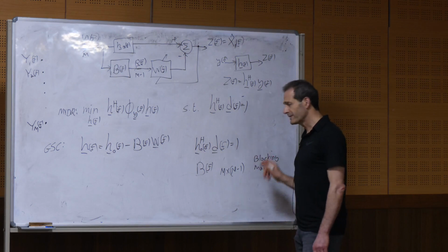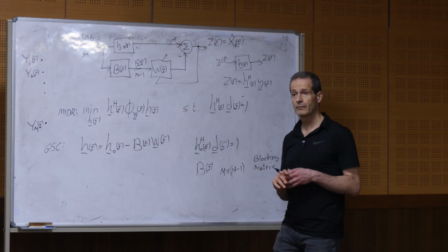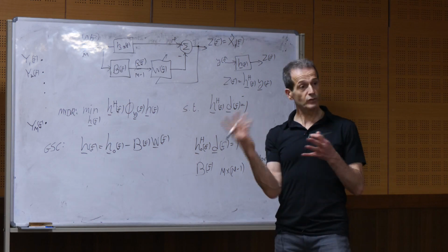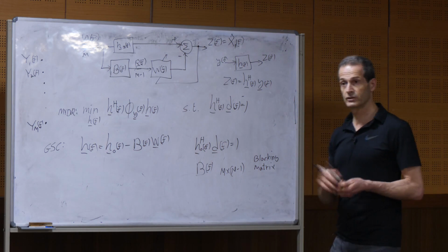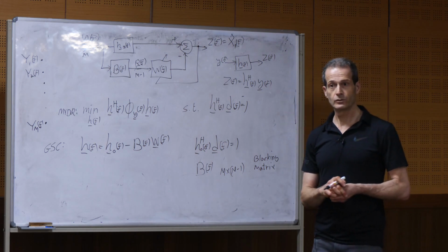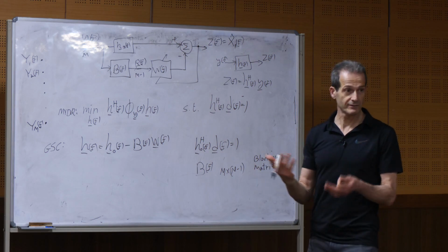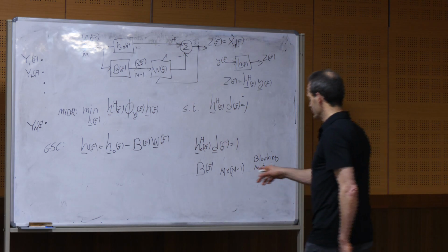So this blocking matrix, we can actually obtain it if we know the model, the relative transfer functions, okay? Just like we showed before. So if we know the relative transfer function, which is the steering vector, we know how to find this blocking matrix.